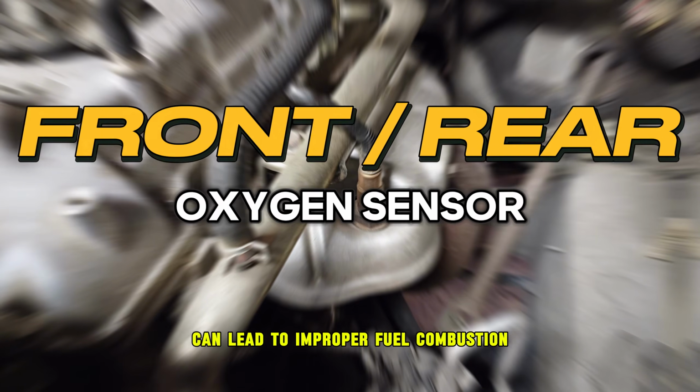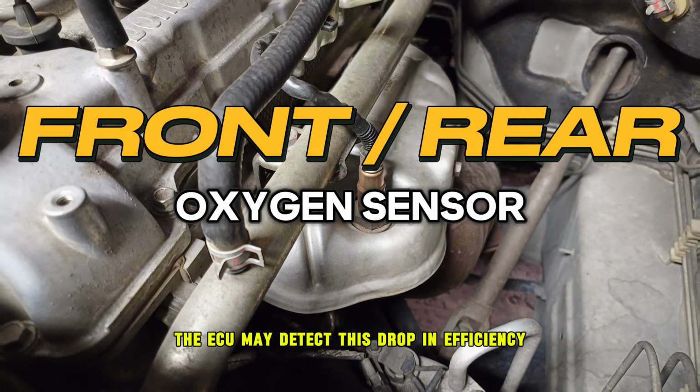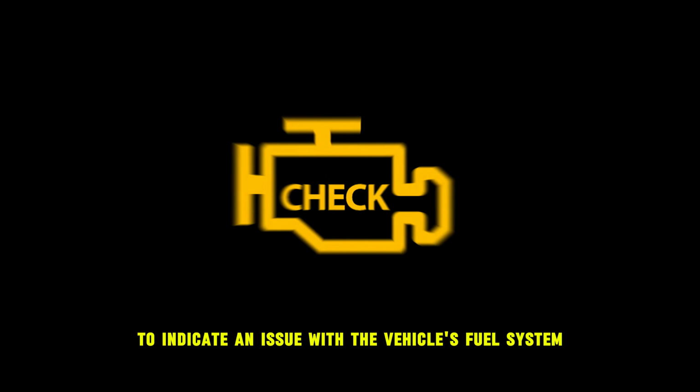An inaccurate O2 sensor can lead to improper fuel combustion, reducing fuel efficiency. The ECU may detect this drop in efficiency and trigger the check engine light to indicate an issue with the vehicle's fuel system.